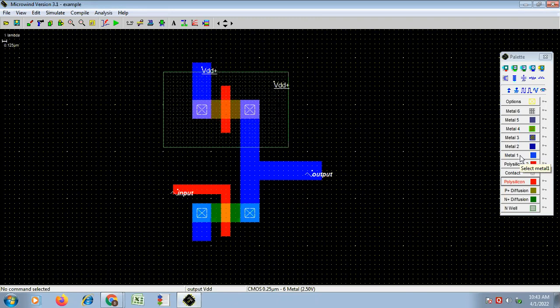Now this is the drain of NMOS. So I will extend this here, and I have to connect this to the ground. This is the NMOS, and now only one connection we have to make: we have to short this gate of PMOS to the output. Now how to do this? You have to extend this up to here, and you have to connect this to the output.